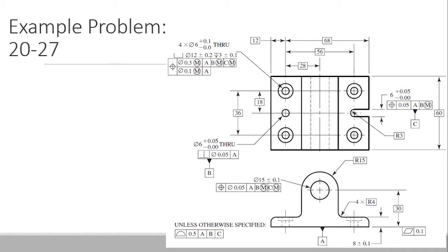Yes. The datum is the corresponding datum axis. Datum is basically the axis of this locating hole. And when this hole is at its MMC, that is what it is referencing to the datum axis. Okay. And the same with datum C. Yes. Okay.